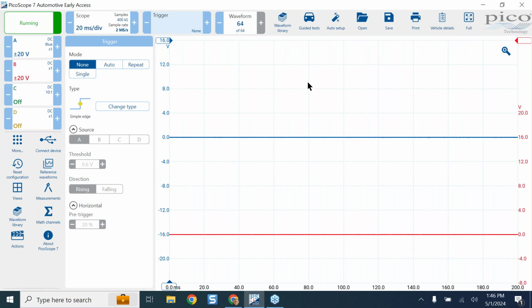And I tell everybody, if you're going to launch a scope, please start with only 2 of these. Please start with no trigger, which is a free run mode. Anything that comes in the input of the scope goes right on the screen. You can go to auto, and auto will work. It will force the signal on the screen if there's no valid trigger point, but it looks choppy. So I get that support phone call that they've got the computer running and it's choppy, it's slow to respond, or it's blocky. I get that word, and it's because they got auto trigger selected and there's no valid trigger point.